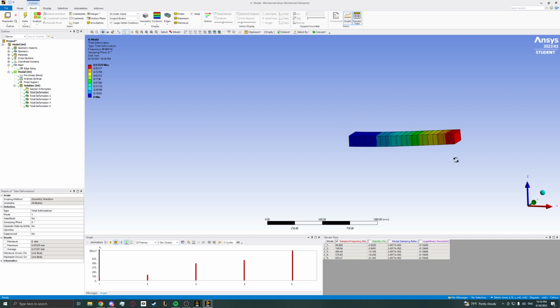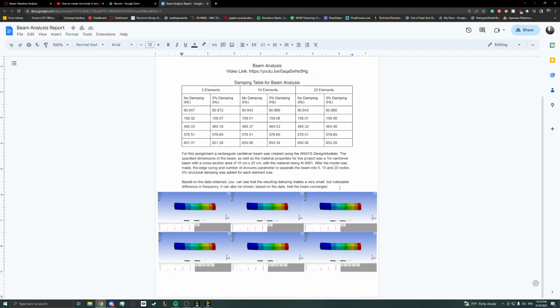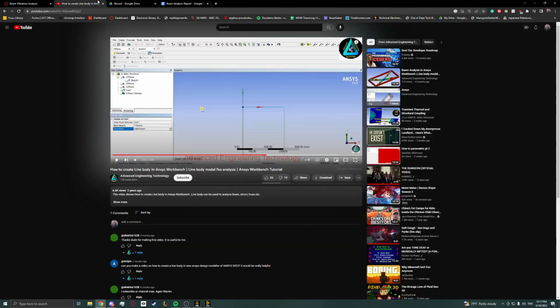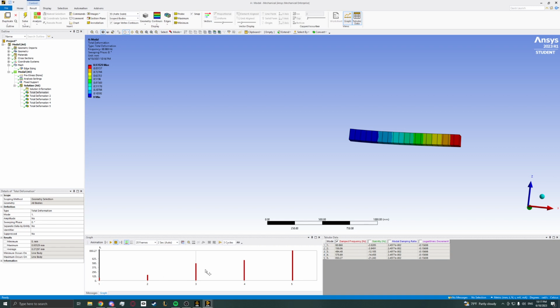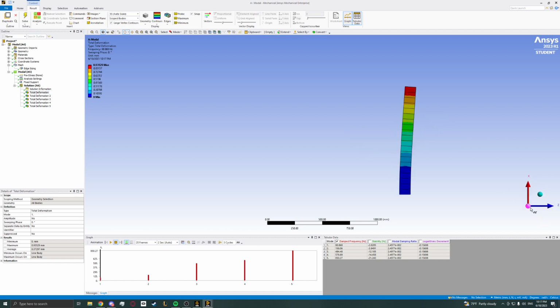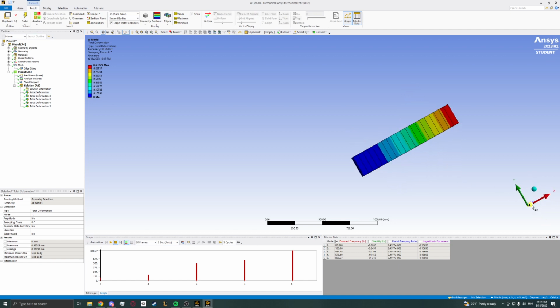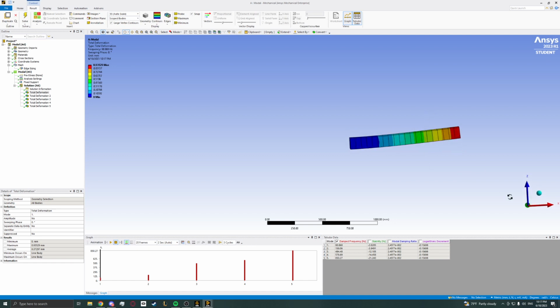And then, so here's gonna be our frequency stuff. You only need 5 of these for each, so off the 10, 15, 1 or whatever. You only ever need 5 of these modes here, so the total deformation 1, 2, 3, 4, and 5. So I think it just solves it 5 different times. I would just click the first one. So this would then be your screenshot here. Just click normal to z-axis.